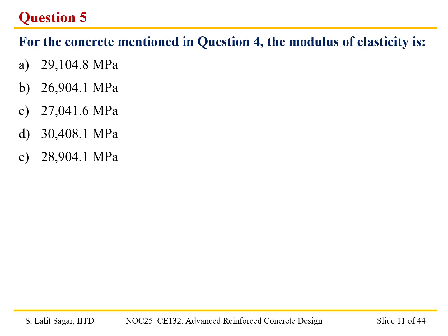Okay, so for those of us who joined now, I'm going to just write down the data, which is going to help you calculate the correct answer. We have F prime C is 30 MPa and epsilon prime C is 0.002. Okay, this is the data from the concrete cylinder test. From that we need to determine the modulus of elasticity. So what is the equation for modulus of elasticity? Modulus of elasticity, that is EC, is given by 5000 square root of FCK.